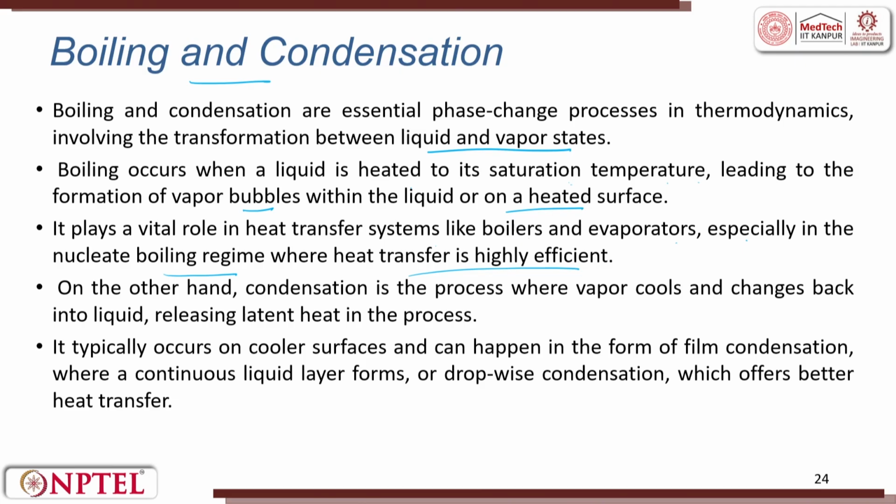When the nucleate boiling regime is there, vapor comes and it gives a high heat transfer. On the other hand, condensation is a process where vapor cools and changes back to liquid, releasing latent heat in the process. If you go back to solidification, latent heat plays a very important role.